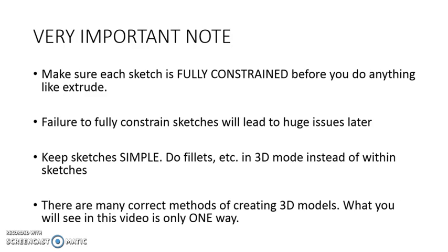Make sure that you keep your sketches simple. You're going to see in this video, for instance, this is one of the main ones that I think about whenever I add this important note. You're going to see me do things like fillets in 3D mode instead of within the actual sketches. What I've found over time is that it's easier to constrain when I don't worry about things like the fillets in 2D sketch mode.